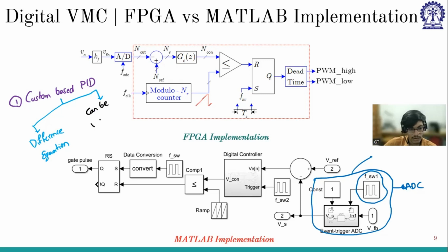So when we consider variable frequency operation, our control voltage should change with respect to the frequency, which is varying. If you use a custom PID block that MATLAB is providing, it is fixed frequency. So it will change the control voltage in a fixed frequency format, and the converter is operating in a variable frequency.